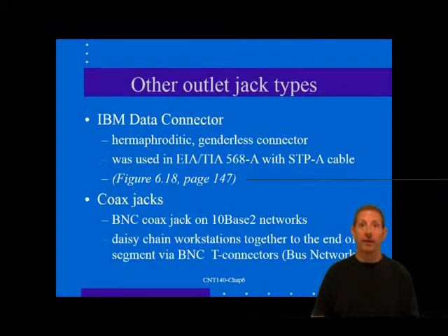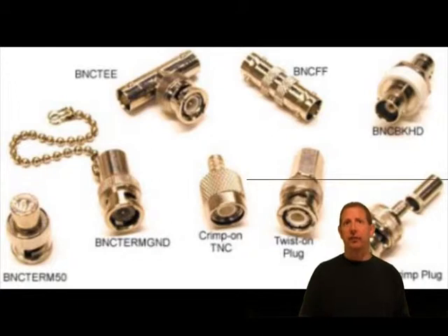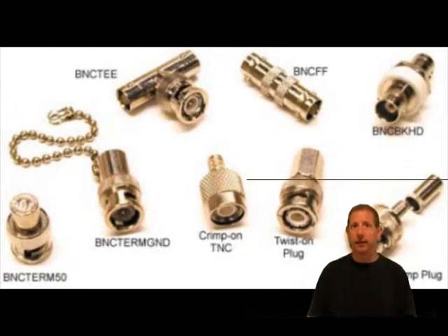From the dual coax outlet connection to the workstation, made with 2 coax jumper cables with 2 BNC male connectors at each end. At the workstation, the T is connected to the network adapter and the 2 cables connected to the T. If the workstation is at the end of the coax segment, only 1 cable is used and a 50 ohm terminator is placed on the other T position.